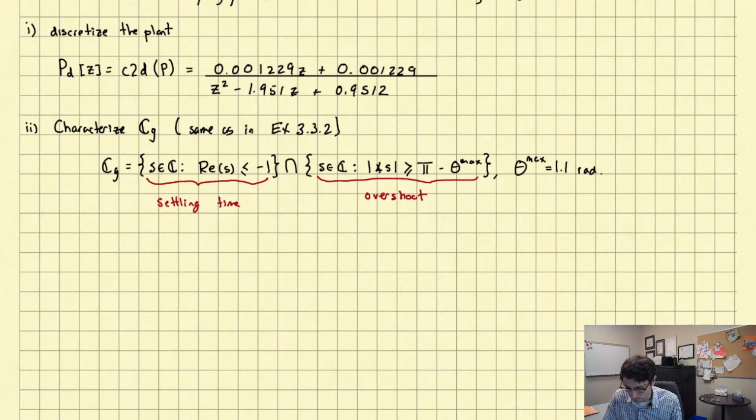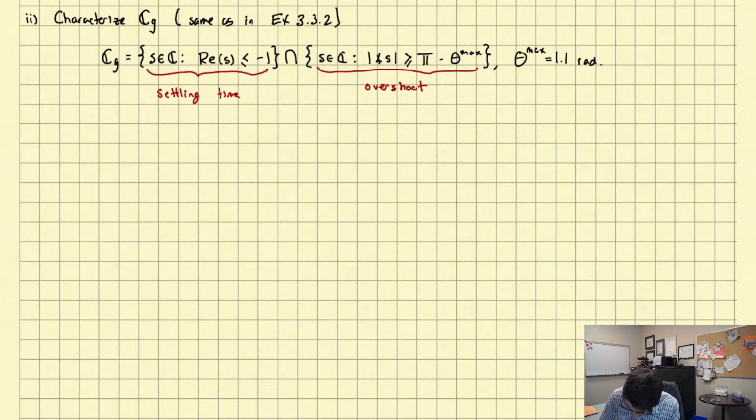Okay, so what do we do next? We determine the structure of the controller. Right, all the comments I said in terms of continuous time apply here, right? You need to pick the type of controller you want before you pick the desired pole locations, because the order of the controller informs how many desired poles you have to pick, right? So if you're doing internal model principle, you'll get some order of the controller. If you're doing practical step tracking, you might get a different order. So at this point, we want to fix the structure of the controller. So determine the structure of the controller.